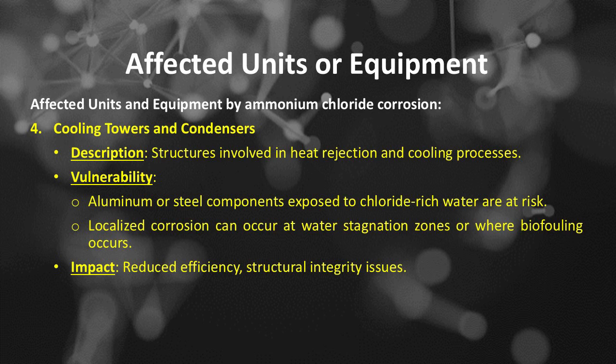Number 4 is cooling towers and condensers. Description: structures involved in heat rejection and cooling processes. The vulnerability of ammonium chloride corrosion to cooling towers and condensers includes: aluminum or steel components exposed to chloride-rich water are at risk. Localized corrosion can occur at water stagnation zones or where biofouling occurs. The impact: reduced efficiency, structural integrity issues.